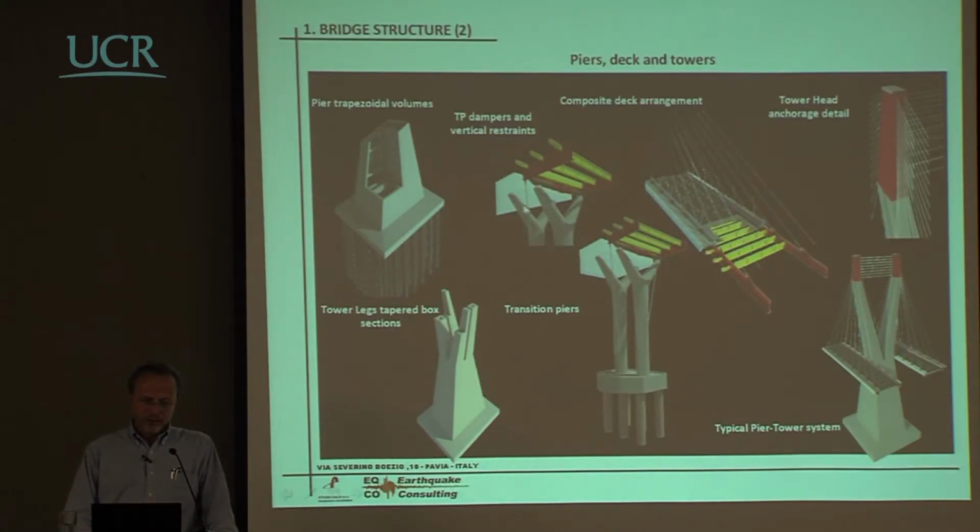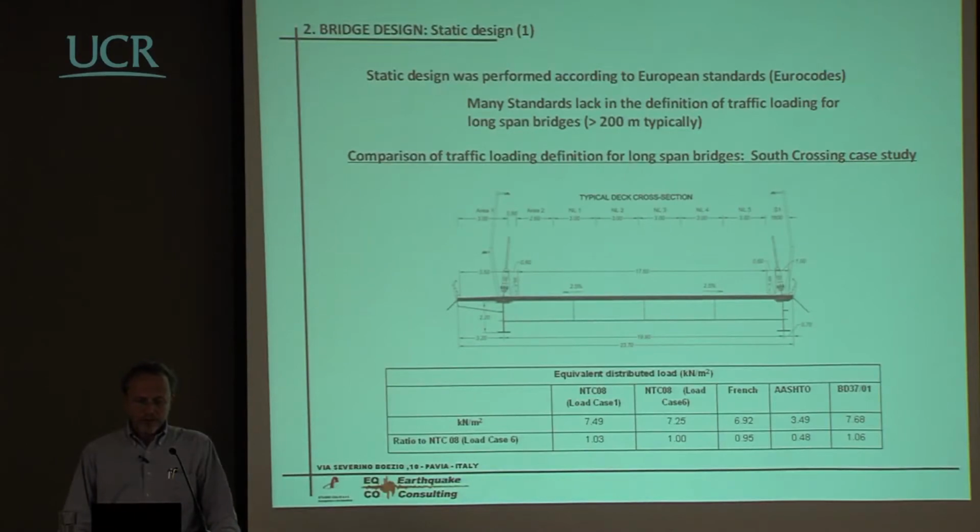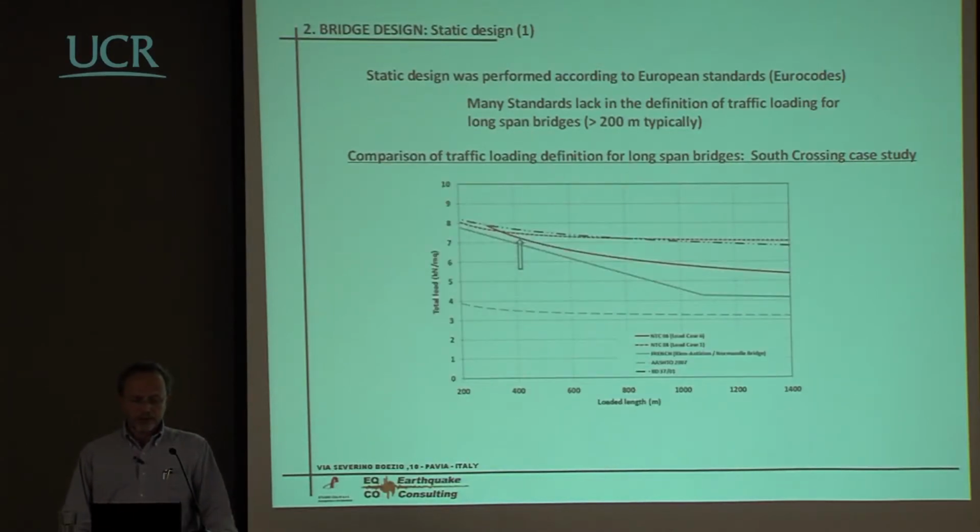And of course, you start from the foundation and you go all the way to the delicate, difficult part where you have to put all the cables to the anchorage of the cables. So the static design was going as I was discussing. It is interesting to see that if you use different codes, you have enormous differences in the level of live loads that you have to use.